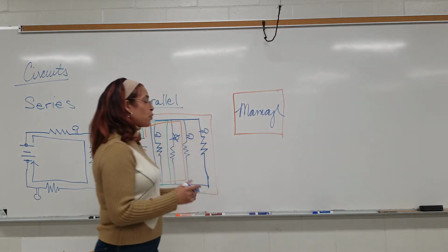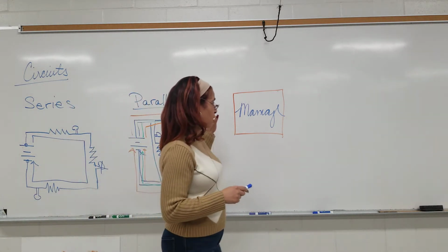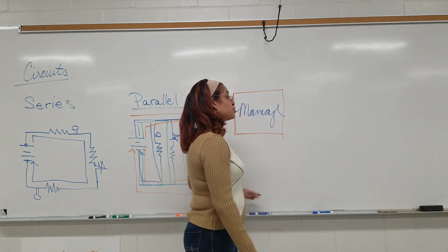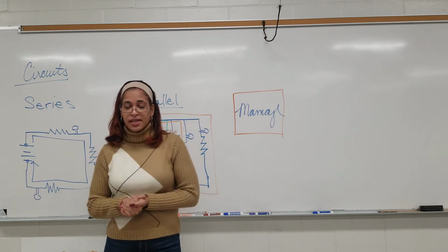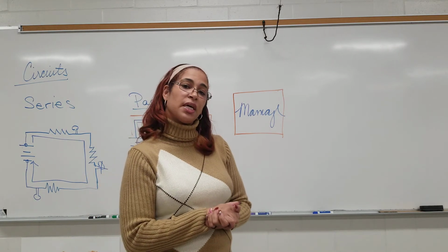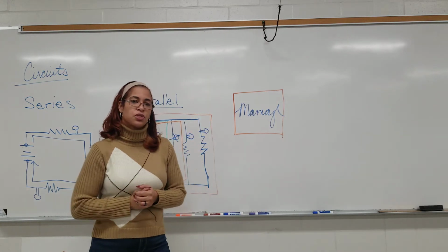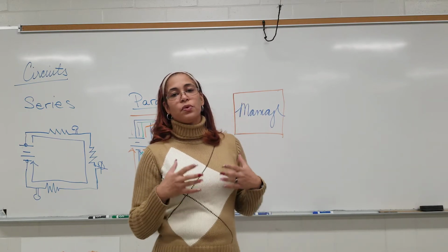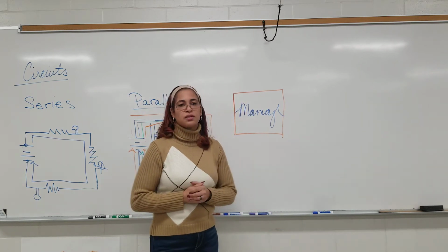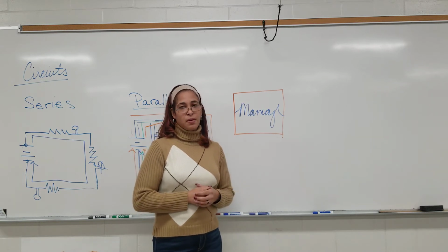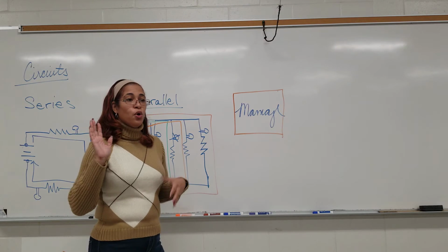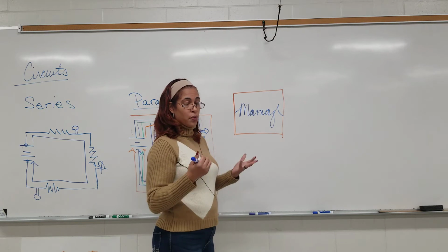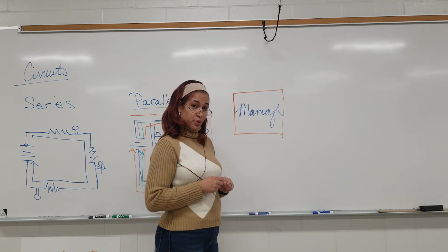Okay, so what I did was I connected, again, you saw that there was a complete flow from point A to point B. Okay, so now your boards are all sitting in the etching solution, so I'm looking forward to seeing what they look like tomorrow when they come out of the etching solution. And all of the copper that was not protected by the ink design that you made would be removed, and the copper that is under the ink design would be protected and therefore would stay behind. Once you get your board, you're actually going to connect them to a battery, and you're going to see what kind of power you produce, okay?